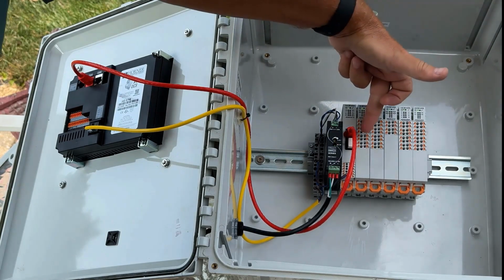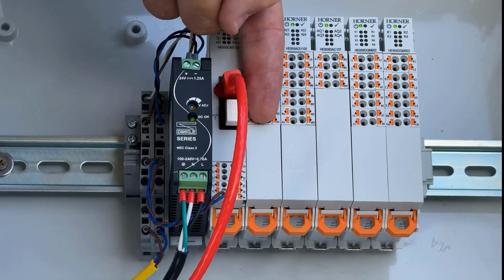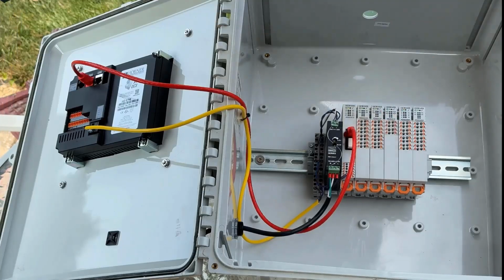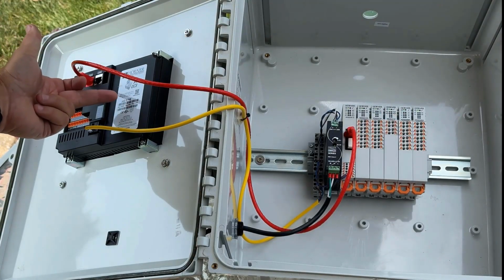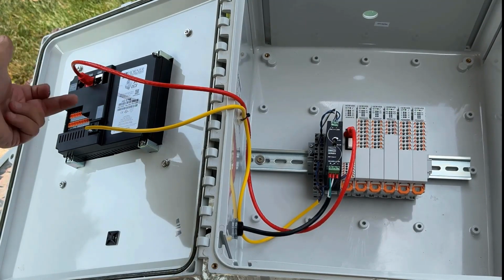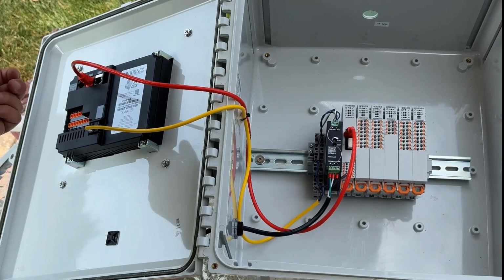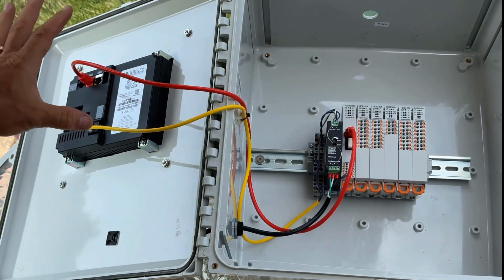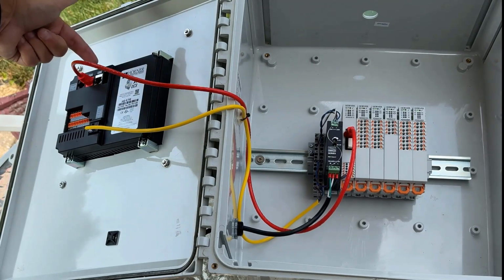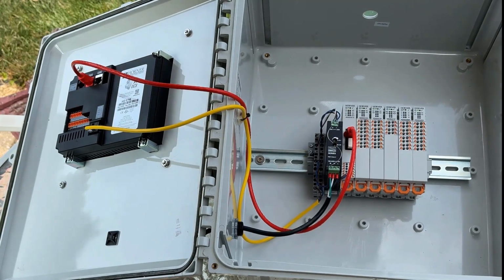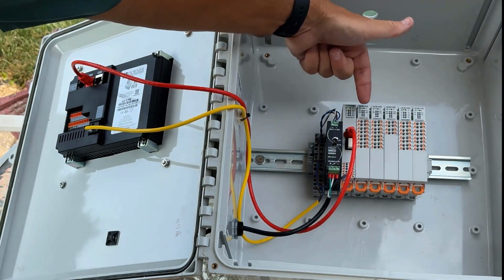And then we cannot forget about termination. In the case of OCS IO, we have got our standard termination plug, and in the case of the X7, either in logic or on the system menu, we need to turn on termination that is enabled in software. We only do that if the X7 is on the end of the network, which it is, and we only terminate the CNX if it is on the end of the network, which it is.